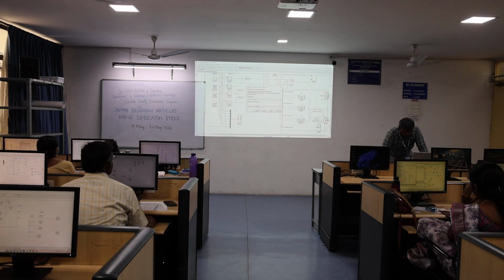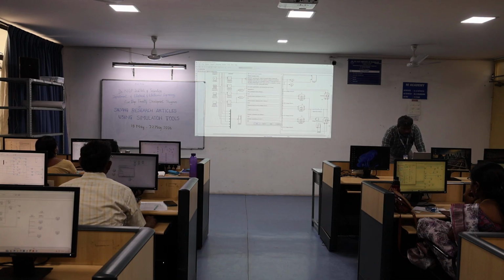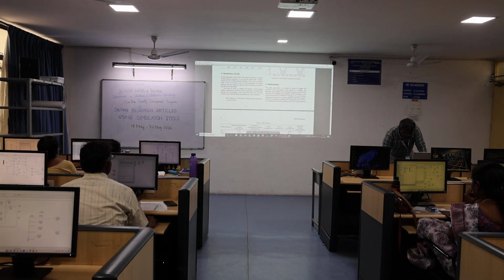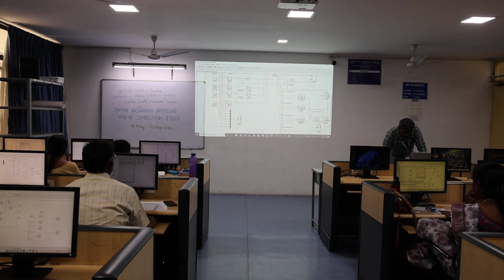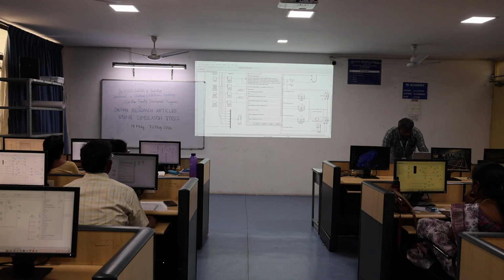For the internal MOSFET, you have the FET resistance on value, and you change it to 0.01, internal 0.01, default value 0.1, you change it to 0.01.